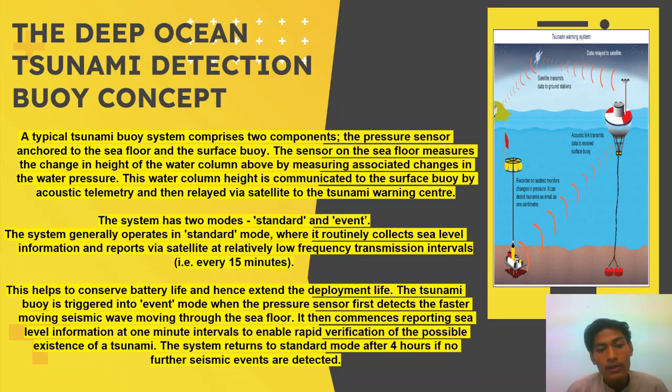The tsunami buoy is triggered into event mode when the pressure sensor first detects the faster moving seismic wave moving through the seafloor. It then commences reporting sea level information at 1 minute intervals to enable rapid verification of possible existence of a tsunami. The system returns to standard mode after 4 hours if no further seismic events are